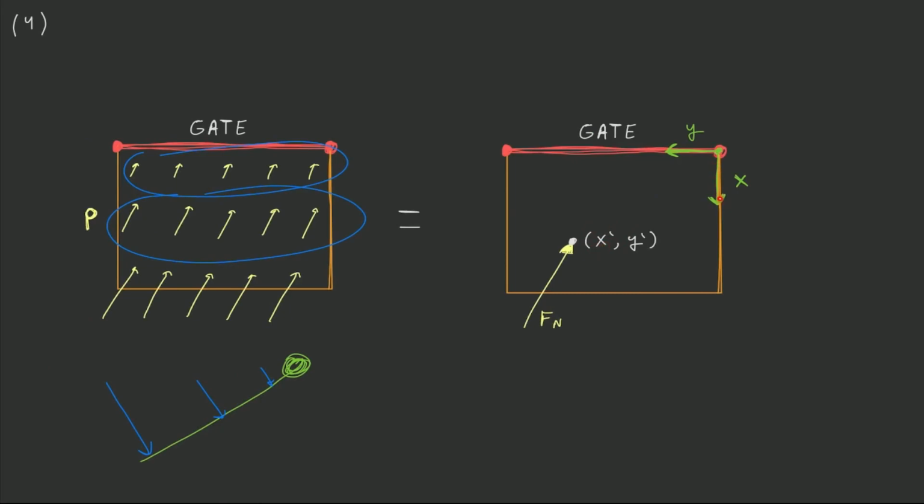If you apply Fn 2.79 meters down this plate, it creates an equivalent moment about the y-axis as the net pressure distribution does. So we are almost there to an equivalent system, because again, we'd much rather deal with a single net force at a single location than the entirety of these line pressures applied over the entire area of the plate. This right-hand side is much easier to manage than this left-hand side. So again, if we apply Fn at 2.79 meters down the plate, then that Fn creates an equivalent moment about this y-axis as this net pressure distribution does.